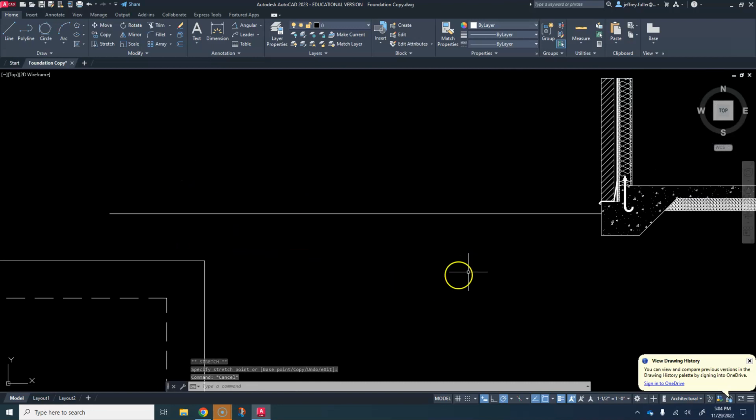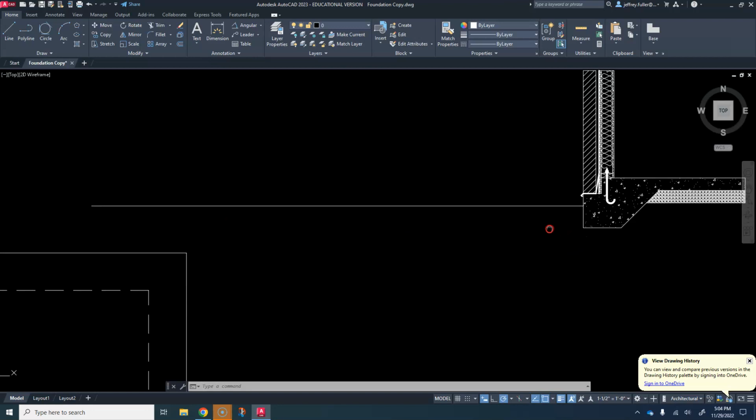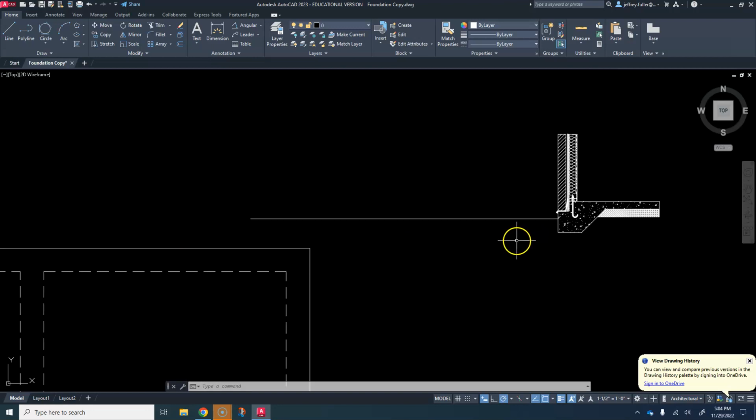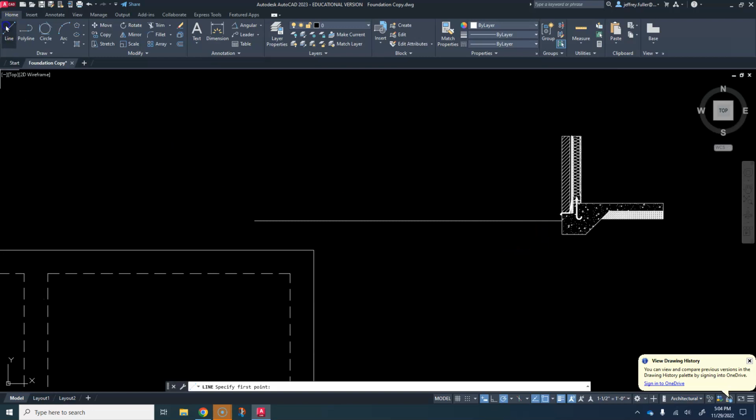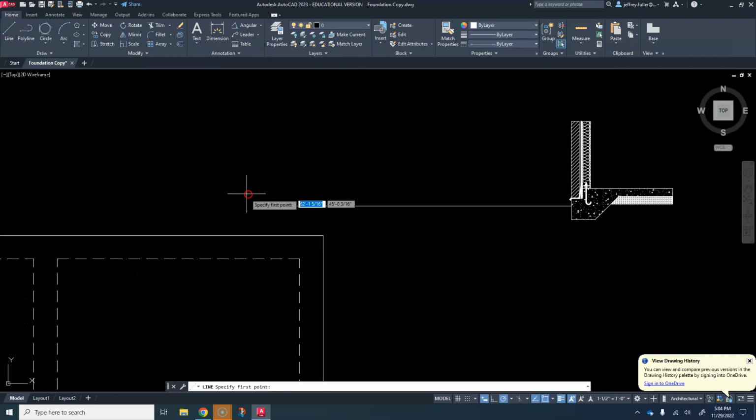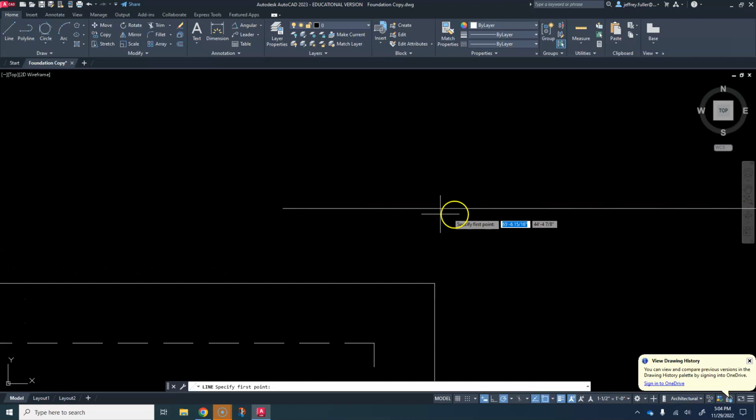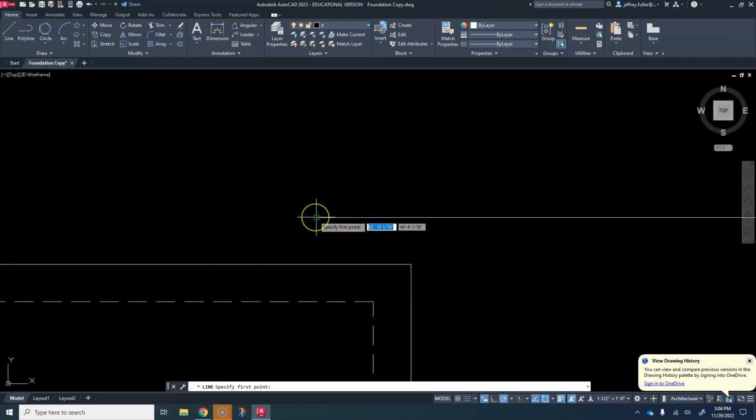What I have to have is a slope, because the earth has to slope 6 inches within 10 feet. Okay, that's how you have to grade the land around the house structure, or at least here in Texas. To get that 6 inches, so this line here is a little over 10 feet, which is cool.